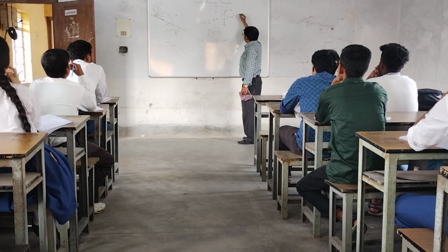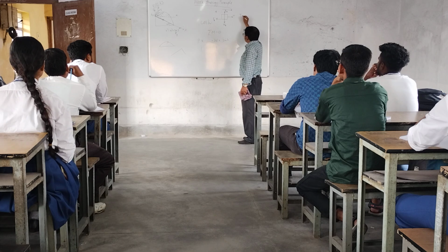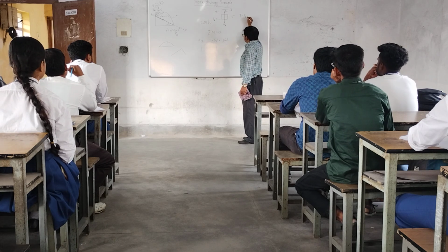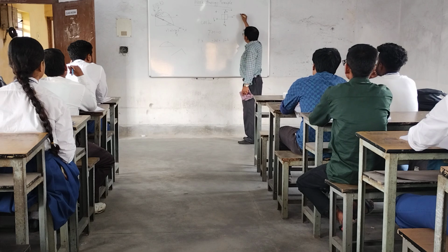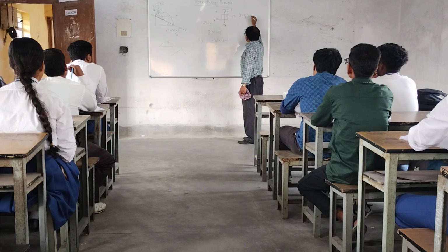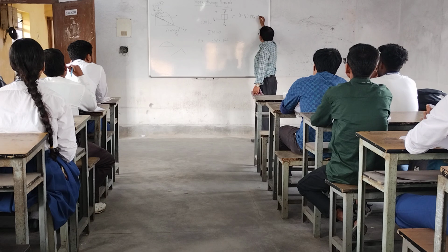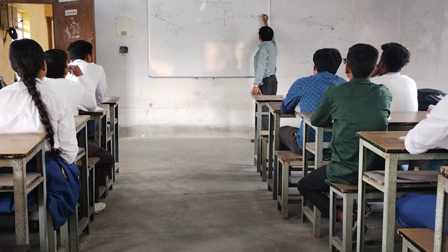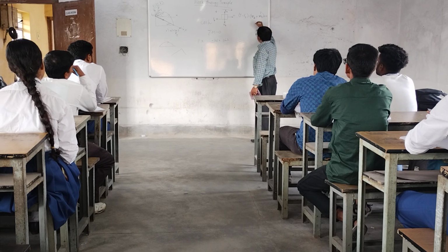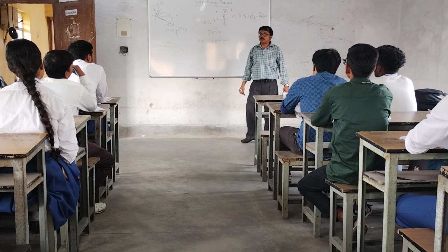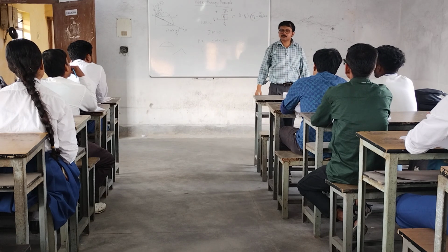Suppose this side is moving, so this you have written correct, E minus the frictional force. So this is your net force, minus the resultant mass of A plus mass of B is coming. You have drawn for body A, so here it will be only mass of A.